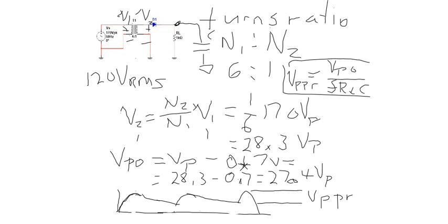What if we could flip it over and use it to fill in those gaps and have more pulses closer together? It turns out there's a couple of ways we can do that. This one we're looking at here is called a half wave rectifier.